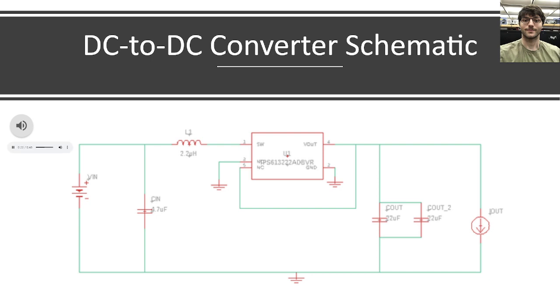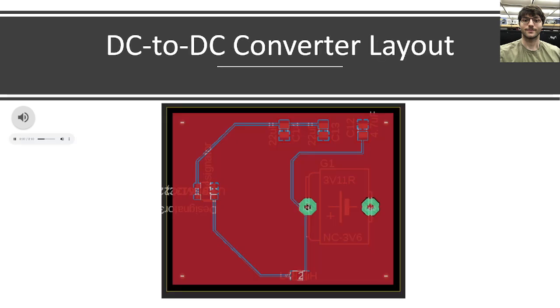The current DC to DC converter design is to handle a voltage minimum of 2.4 volts and a voltage maximum of 5 volts. The converter is also set to have a maximum efficiency of 88.1%. The DC to DC converter acts as the safety net for the device and helps the device perform as efficiently as possible. This is the continuation of the DC to DC converter layout, which shows the circuit's wiring layouts and how the PCB will be designed in EagleCAD.